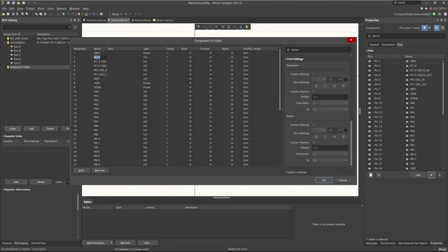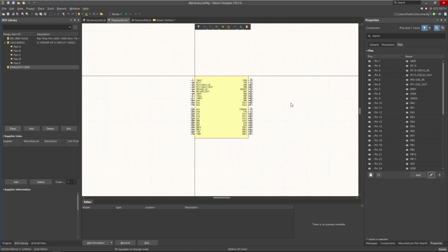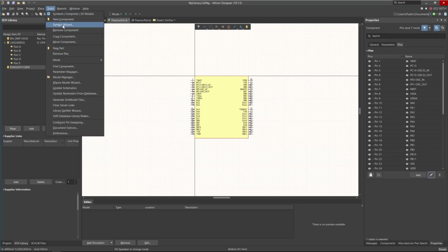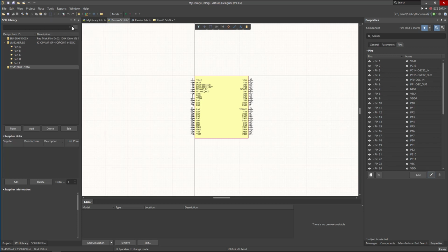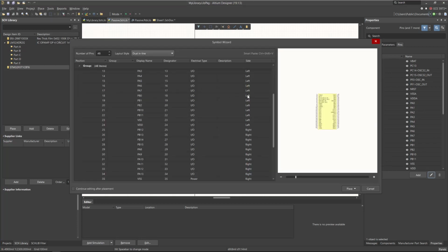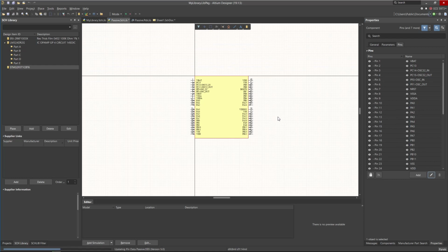This is another way. Now, one point I would mention in here is that the symbol wizard is editable, meaning if you click on the symbol wizard again, you will see the same component you have created with the modification you made on the schematic symbol, and this will allow you to come back in here and edit it. This is also a very handy and very important feature. I like it. It's not like starting a new component. So this is a very, very nice feature. So no change to this.